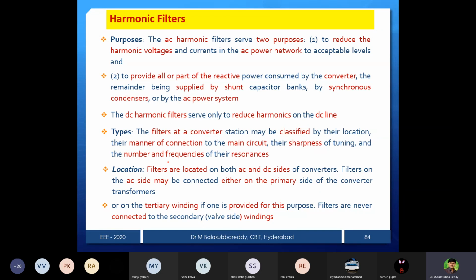But what about the large transformers in the substations and all? In that large transformer, we require some cooling mechanism, air blast or air cooled or oil cooled, like that, and some office purposes also may require power. What is that, substation office or something. So for pumping and all mechanisms, whatever auxiliary equipment is there, we require power. And who will supply that power? You cannot tap from the 11 kV substation or 33 kV substation directly.